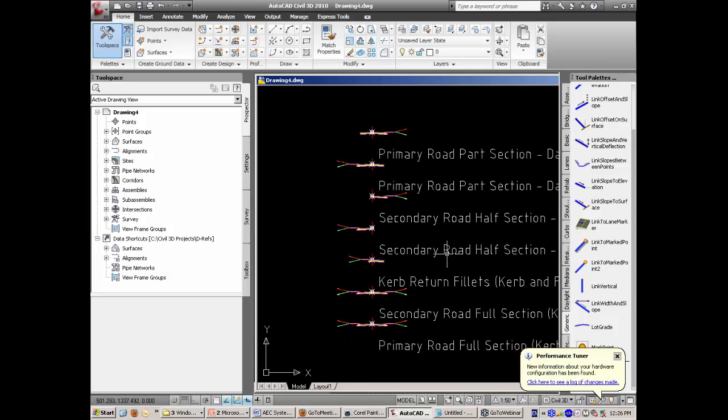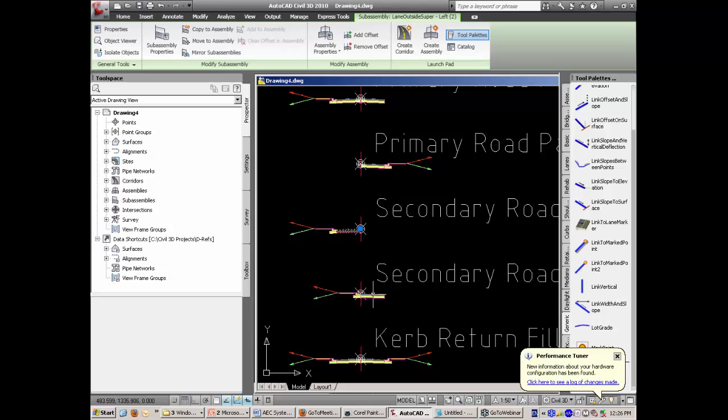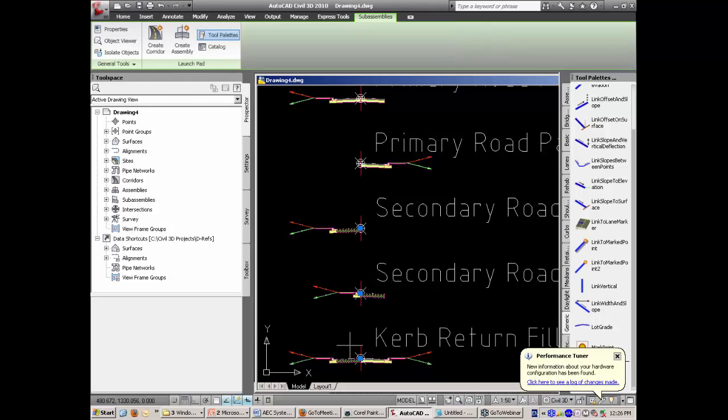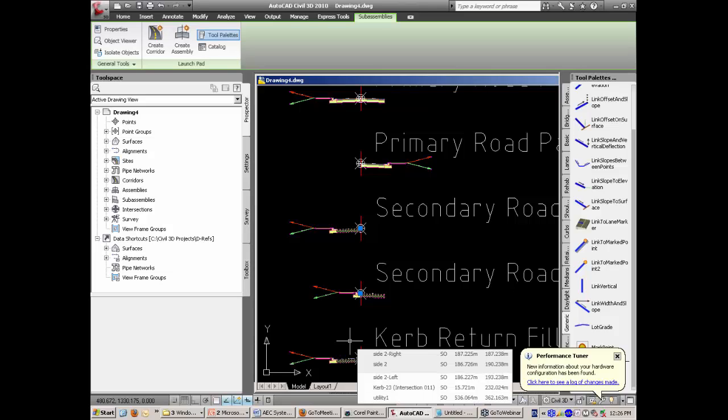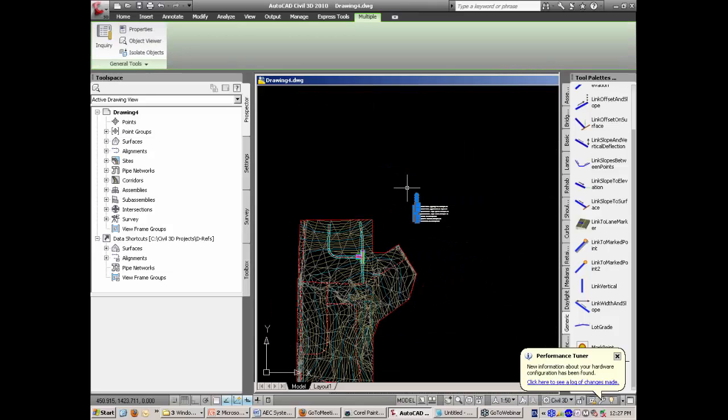The important thing here, which we normally skip over, is the subassembly components. So let me just check your screens have caught up. What we've got here effectively are subassemblies, and the components I'm highlighting, the main road, they get stretched automatically to match with the various strings for the edges and bits and pieces. Now when you look at what's happening here, there's no reason that that component I'm highlighting can't be my generic link for my tunnel. So essentially all we do is replace these assemblies you're seeing now with the equivalents from the tunnel that we just did.